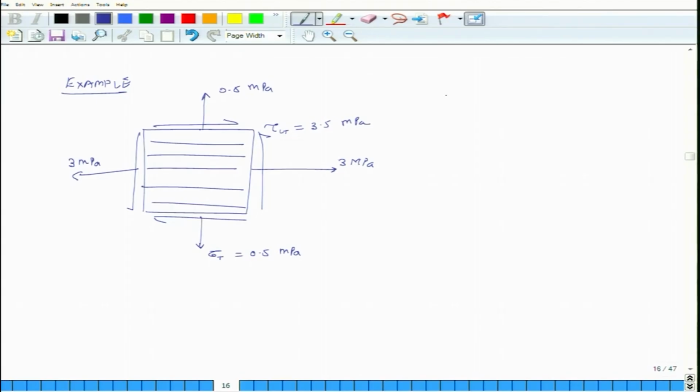and the material properties of the lamina are such that EL is equal to 14,000, ET equals 3,500, GLT equals 4,200, nu LT equals 0.4, and nu TL, which is not independent, we can actually calculate it, but here we are just given the value, and that is equal to 0.1, and these first 3 entities EL, ET, GLT, they are in megapascals.